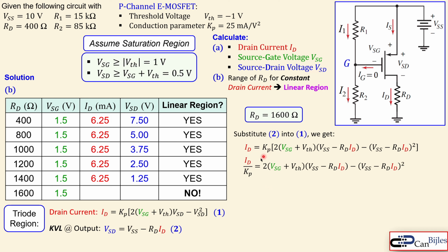Now when you work it out a little bit further, and also for your solve for later, we can divide by the Kp now. That will be then this. You have now this expression on the right side. Let's substitute the values we know. We know the Kp. And by the way, we have now only ID as unknown, so we can solve this.